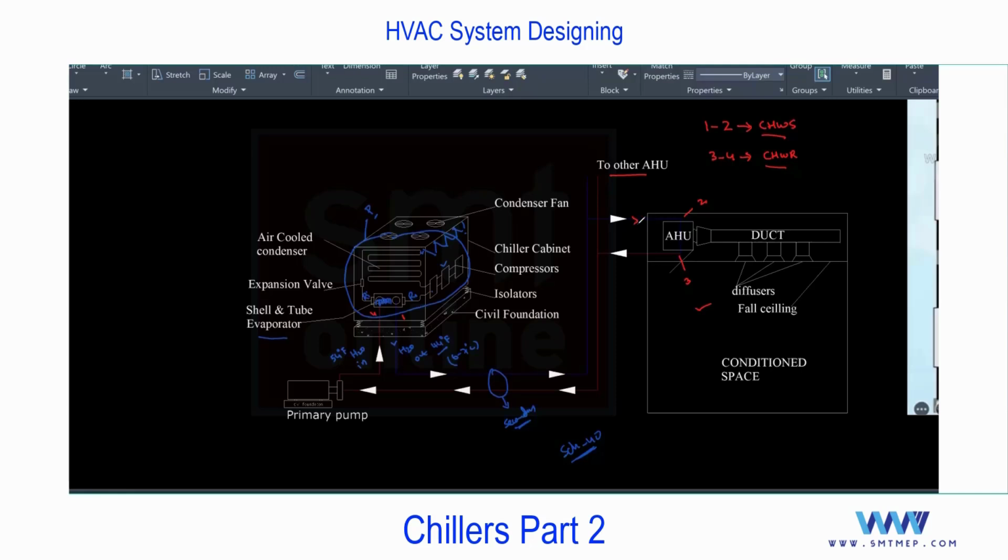Instead of connecting this pipe from the condensing unit, we are connecting the pipe from the chiller to supply the chill water instead of the refrigerant. So the rest of the things inside, we can provide the fresh air. All this detail you can consider the same as a ductable split, what we discussed, like coil piece, then supply, return, etc. Okay, and you see this, the cooling effect or the heat will be extracted from the room air, and the